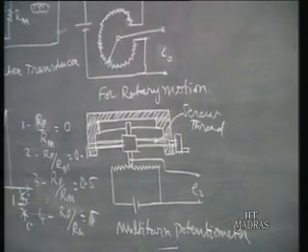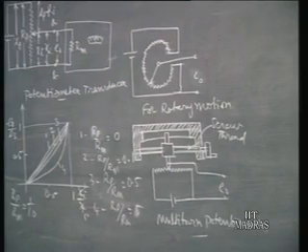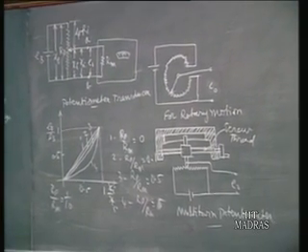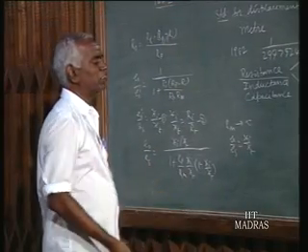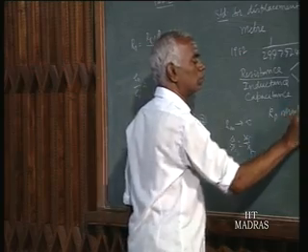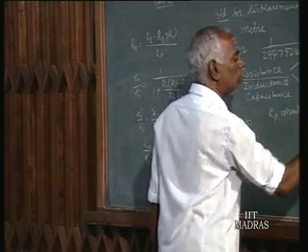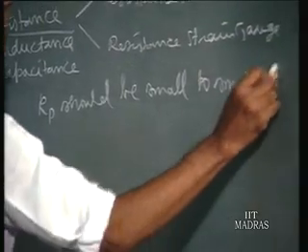But in selecting the Rp value, you have to be a little bit careful, because it has certain opposing effects. Rp should be small compared to Rm in order to have a smaller loading effect.